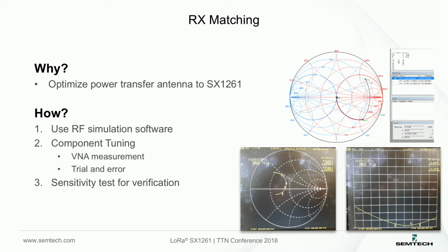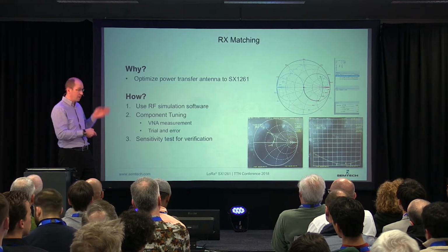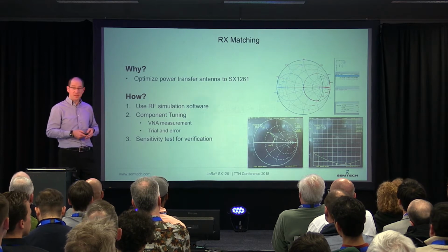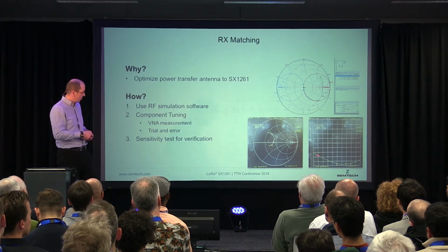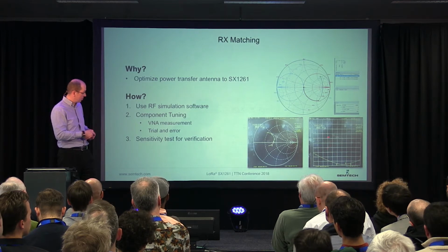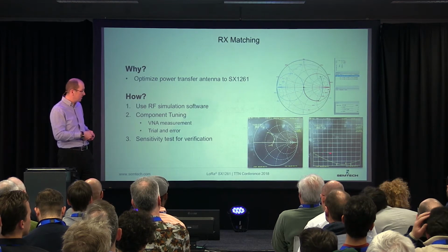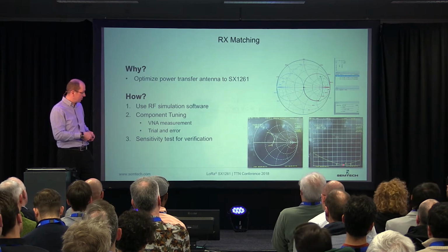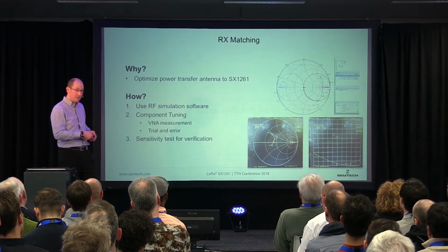Ideally speaking, you should be here right in the middle, in the frequency of interest. And you can check also that you've minimized the loss. Here it's the mismatch loss versus frequency. So if you have the minimum loss, then it means that you're matched.